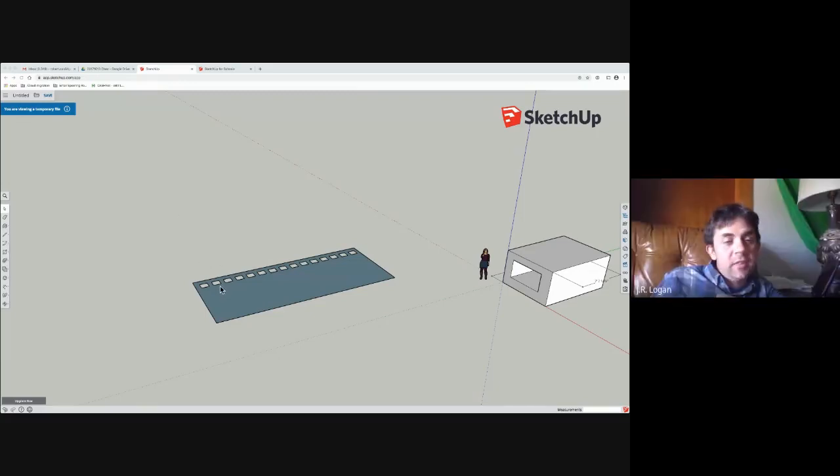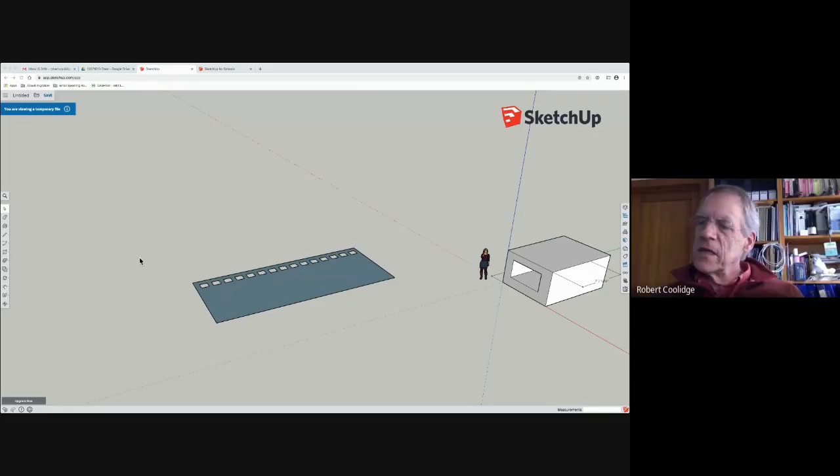Okay. Well, I'll try that at home, because I think that's something I want to try. Yeah. So one other frustration you can run into, especially when you're doing those extrusions, trying to make a spun object or something, is SketchUp has built into it something that won't let you make little teeny tiny bits that are too small, like less than 1/16 of an inch or whatever. So occasionally you'll have problems where you try to turn an object and it's got little tiny holes in it where the little faces were too small.